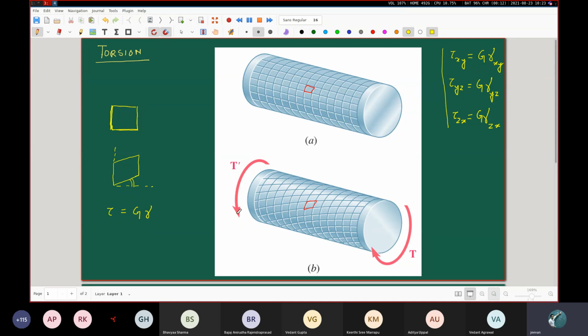Now, coming back to a very important thing which one of you asked. You see, there are some circles present in the undeformed configuration. If you consider them like discs, they are parallel to these discs. If you line them up together, they're all parallel to each other. Now, in the deformed configuration, the question is, are those circles remaining like circles? And even if they are remaining like circles, suppose you consider a circle like this from within the body. Question is, after the deformation has taken place, is it